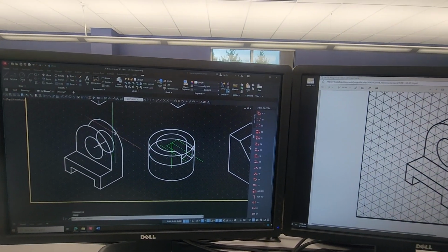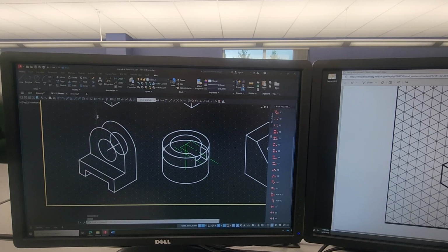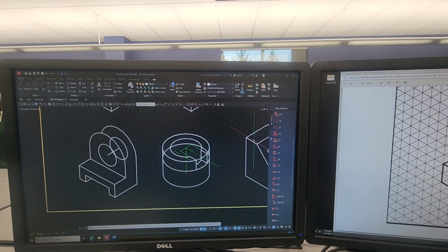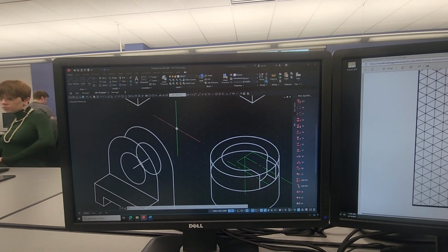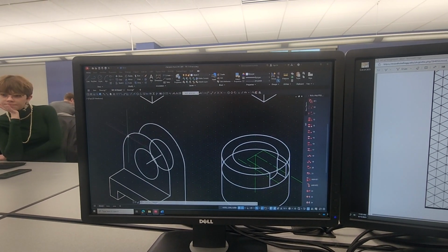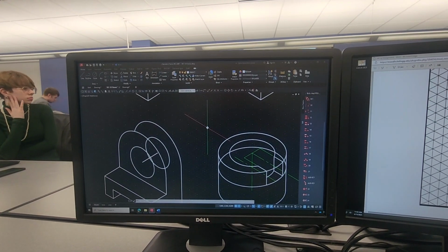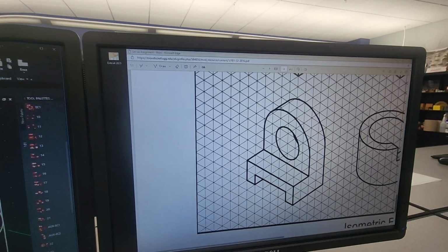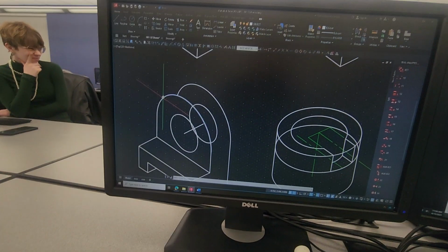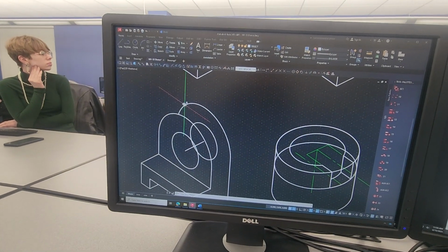The next one is this. See up here? You'll recognize there's got to be some type of a tangency across there. But here's where we have a misnomer, because that's not actually a tangency. It's supposed to be, but in this configuration, working in ISO circles, AutoCAD doesn't recognize a tangency between an ISO circle and an ISO circle.